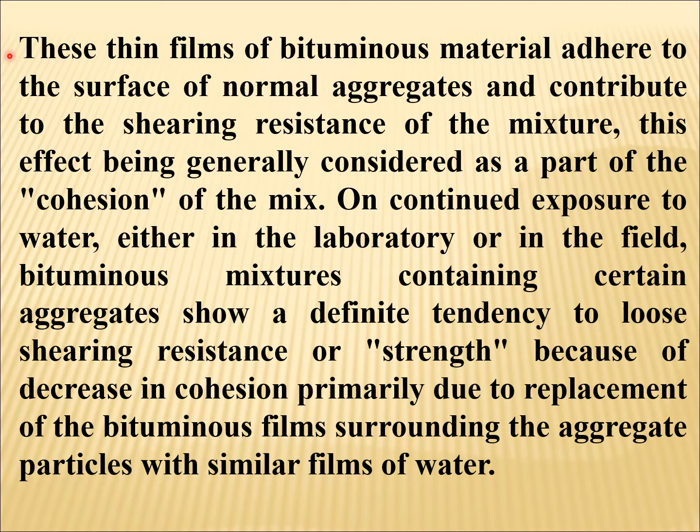These thin films of bituminous material adhere to the surface of normal aggregates and contribute to the shearing resistance of the mixture, this effect being generally considered as a part of the cohesion of the mix.